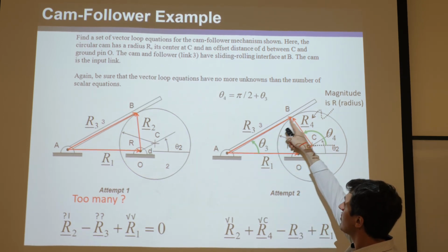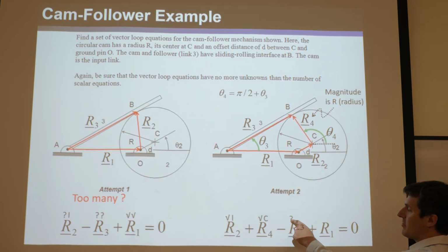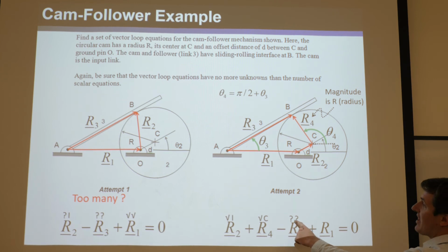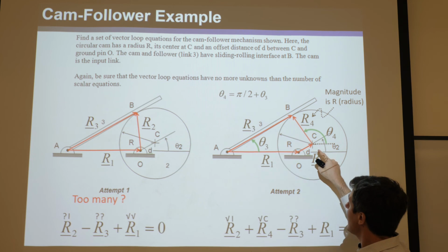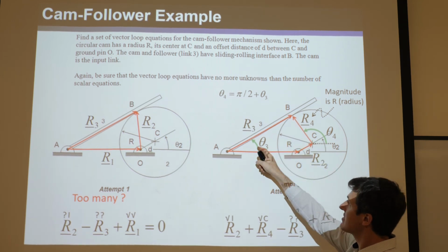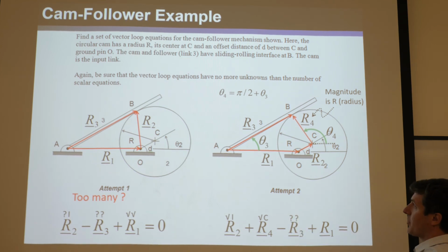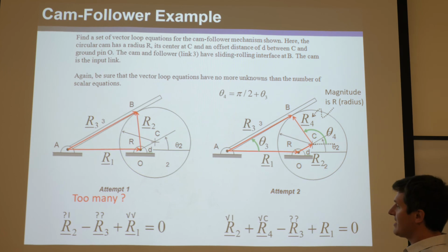This is going to shorten or lengthen as this rotates off axis. So that's a question mark. We don't know that. Okay, and we don't know the angle either. Theta 3 will certainly change as theta 2 changes. As this moves, this will get bigger or smaller. Okay? So that's a question mark. But remember, that creates a function with theta 4, which is why that's C.